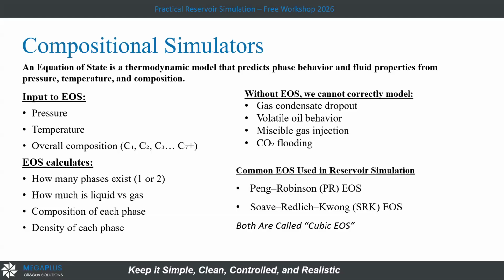and then the oil will come and produce the residual oil. But the third part is called miscible or carbon dioxide flooding, in light oil. Maybe we can use gas injection in a condensate reservoir, or if we have a very light oil that is irreducible or residual, we will inject carbon dioxide. It will dissolve in the oil.